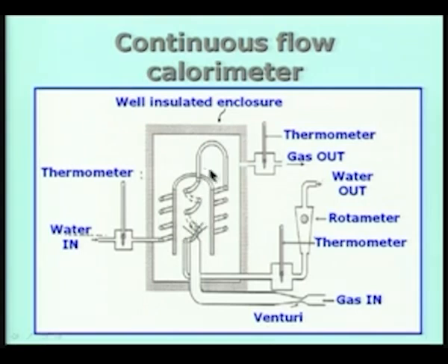That is why we have an elaborate cooling arrangement, so that any water which is formed during the combustion process condenses and is in the form of a liquid rather than a vapor. Therefore, the heating value which we are going to measure is called the higher heating value, because the water vapor or the moisture which is formed during the combustion process is in the form of liquid.